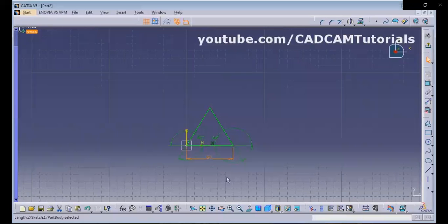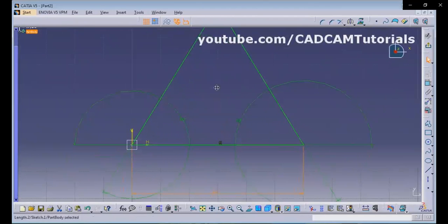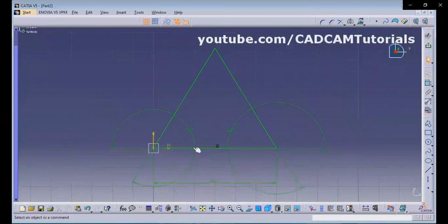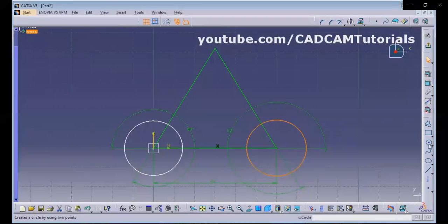Then you can zoom it using this tool here, then pan it using scroll button pressed. Then next is to create the circles. For that we will take this circle command, give the center point and give the other point. In this way we will create all the three circles, second and third.